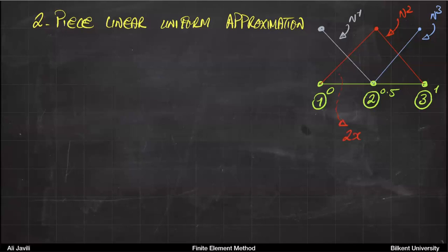And then it has this right piece, which is minus 2x plus 2. Okay, so minus 2x plus 2, again, as you can see, if x is 0.5, then you get minus 1 plus 2. It gives you 1, so it gives you 1 at node 0.5. And then if you look at this one again, it also gives you 1 at node 0.5. Okay, so that is N2.